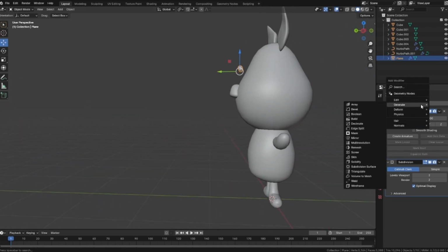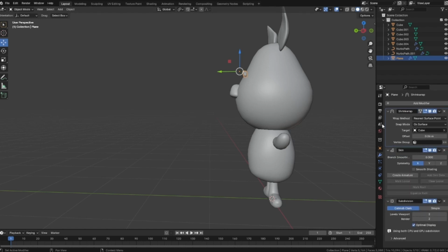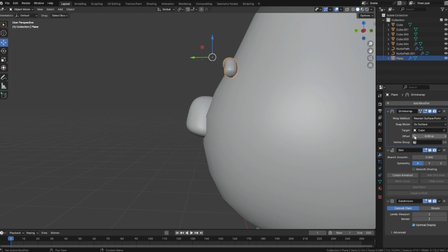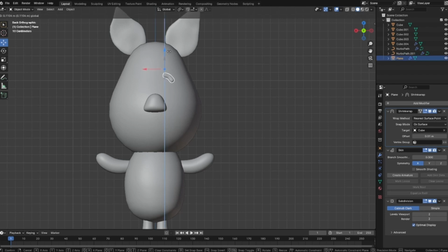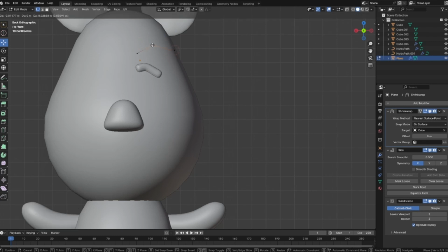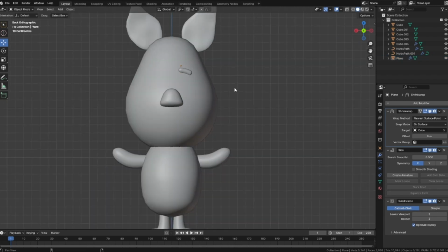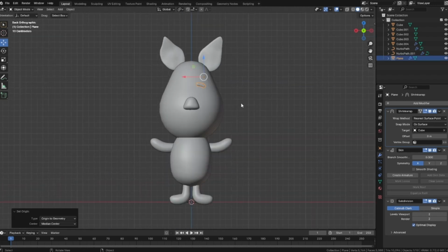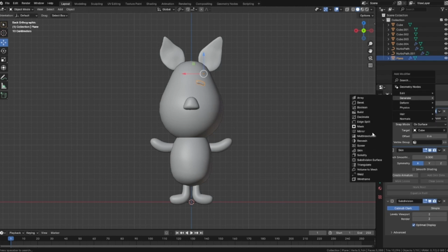And in the side view, add a shrinkwrap modifier. And I drop the head and move it in the top. Set the offset to 0.01. Select this, move it upward. Sometimes shrinkwrap creates some problems. Make it 0 and rotate like this, something like this. Select, then add a mirror modifier.